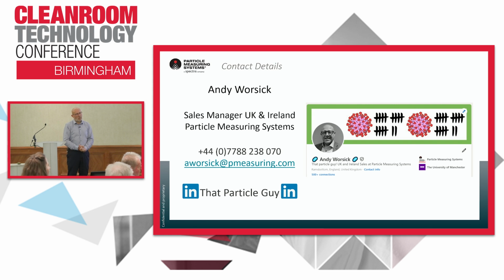But facing upwards should still continue, because there's no difference between the production line, HEPA filters on top, and the risk point down, and we are facing upward based on the ISO. I still consider having it upward, but not sampling directly from the HEPA filter, because in many applications we are very close to the HEPA, like a particle checker. We're not expecting anything to come from the HEPA filter because it's already tested. But we are expecting it to be nearby the risk location, which is the direct integration area where the operator does the process. So it will be close, but still facing upwards to the HEPA filter if it's a laminar flow.